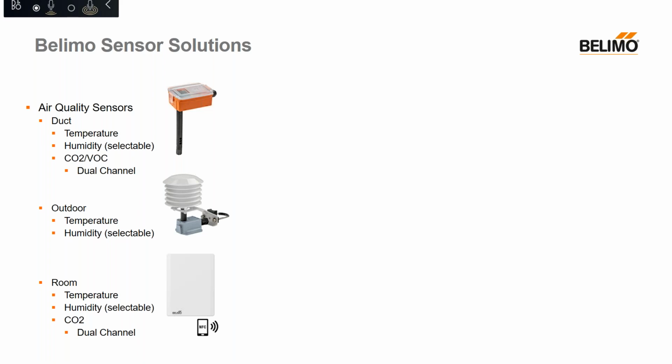This is now a really important feature because as of last year, ASHRAE has updated their 62.1 guidelines, where they're now recommending controlling humidity based on dew point, as opposed to the way it used to be, which was a recommendation to control relative humidity. So again, not only are our air quality sensors here to help your facilities meet these new readiness guidelines, but they'll also help your facility come up to speed with this new ASHRAE 62.1 update.